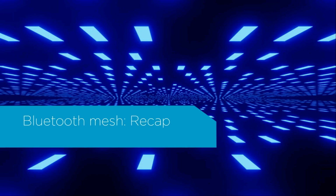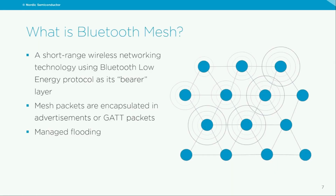Let's do a quick recap of Bluetooth Mesh. What is Bluetooth Mesh? It is a short-range wireless networking technology using the Bluetooth Low Energy protocol as its bearer layer. Mesh packets are encapsulated in BLE advertisements or GATT packets. Mesh networking helps to extend the range of communication for normal BLE devices through something called a managed flooding approach. In this, some of the nodes in the network act as relay nodes. They relay the packets they receive, thereby increasing the range of communication. This way, several nodes in the network can communicate with one another or with nodes that are further away from them.